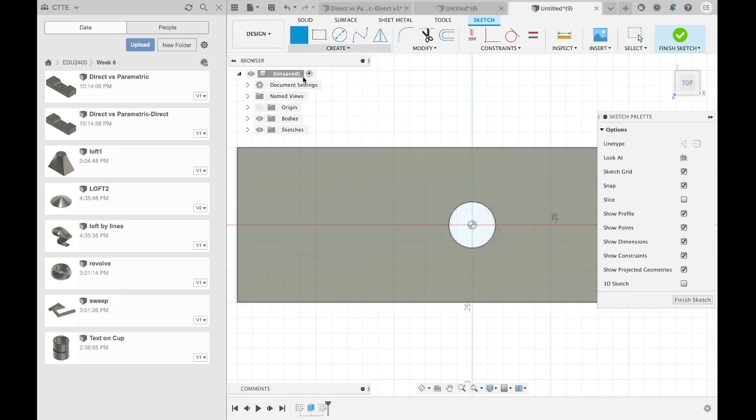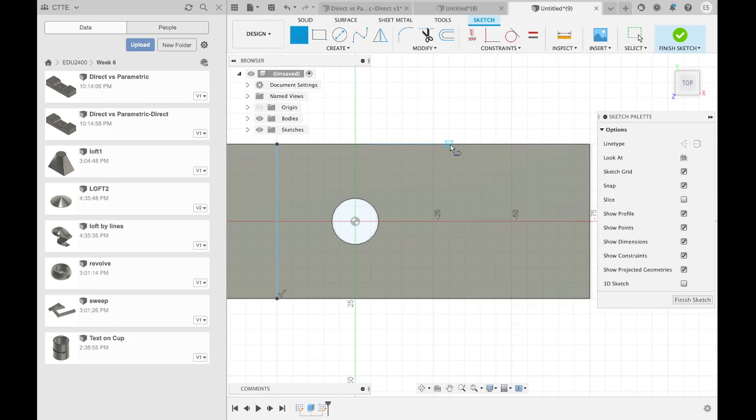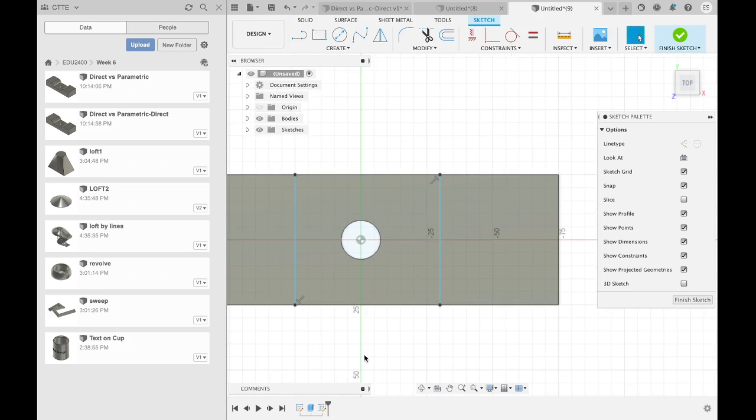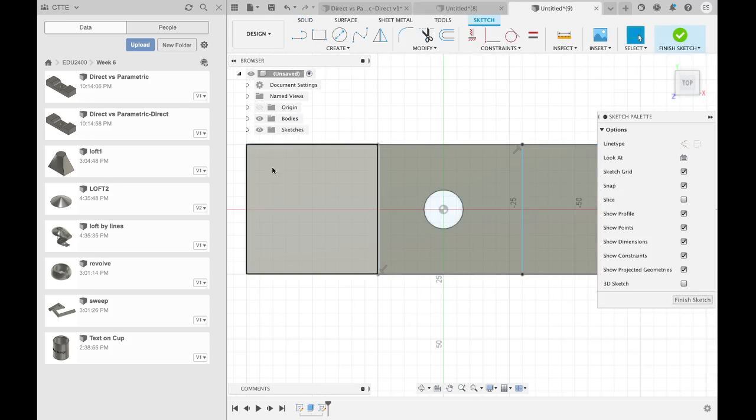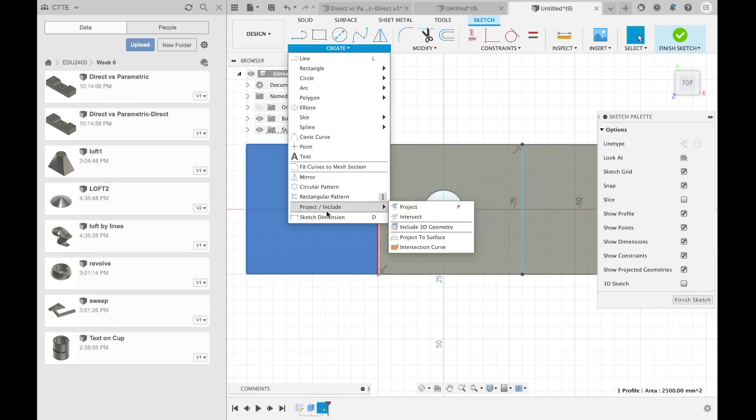So we are drawing two lines. Let's say like here and to there, and then let's draw another line, two lines. We want to make these shapes. That's why we draw these two lines, and the distance from this line is 50. So the distance from this one to this was 50. We can set the actual size by adding a sketch dimension.